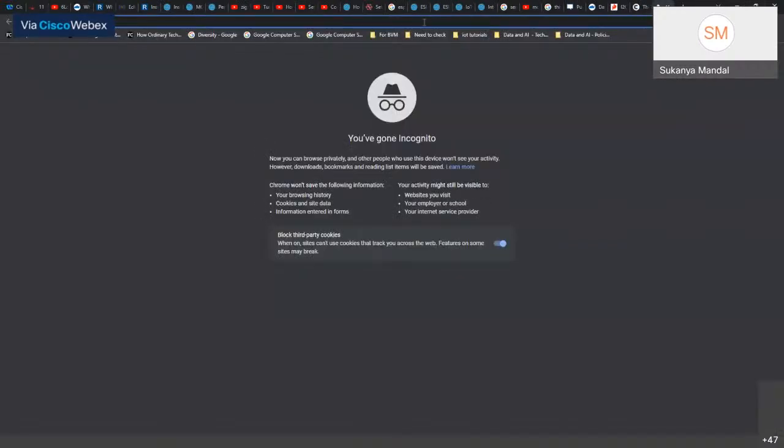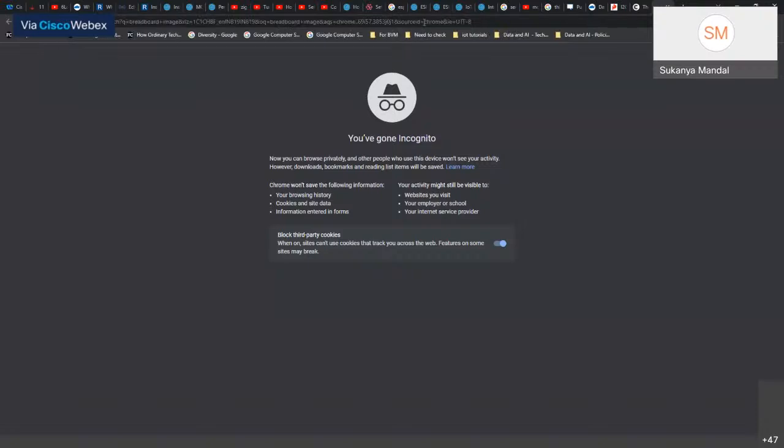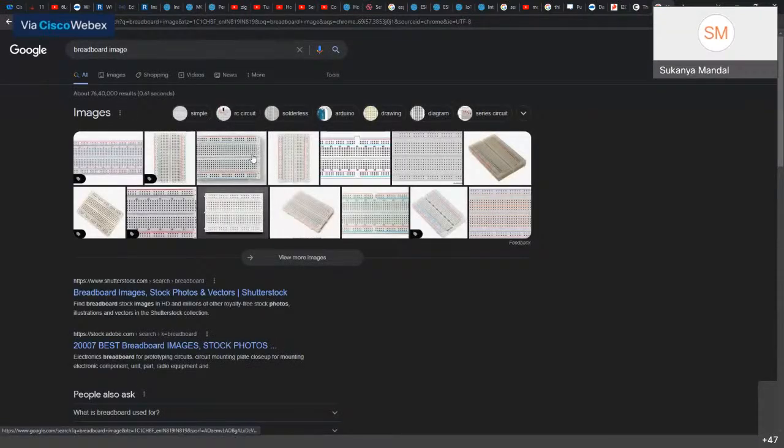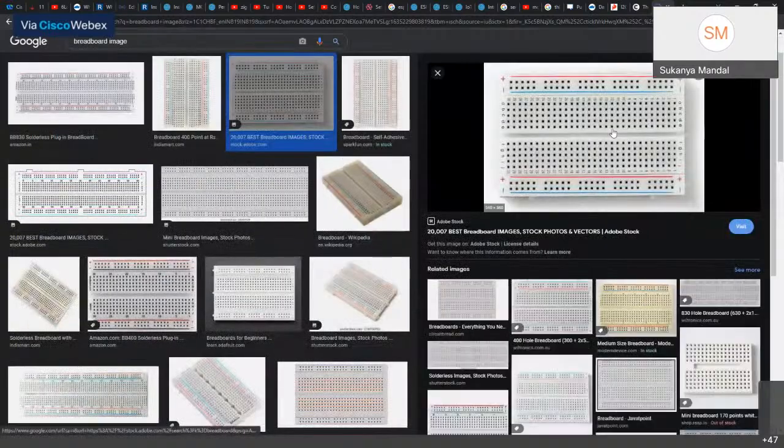Let me pull up a breadboard image. If you look at this image, this A B C D E F G H I J. So A B C D E is in series, F G H I J is in series, and here plus is in series, minus is in series.